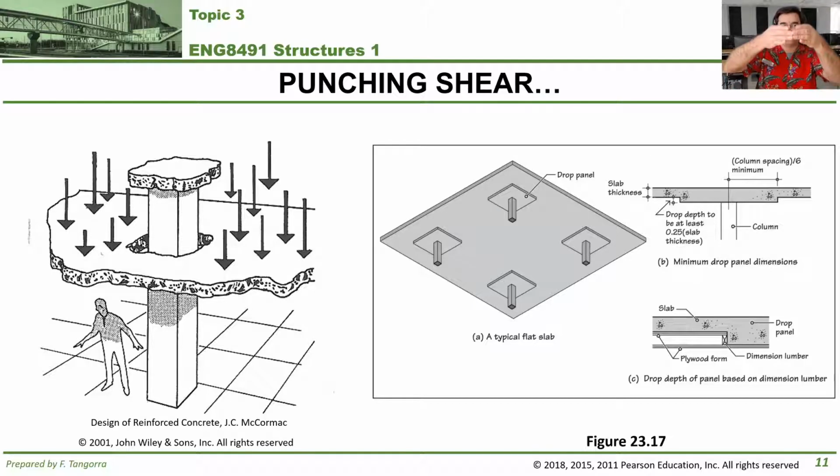But as you get closer to the slab above it, the area of the column is expanded much wider. And that's what the drop panels do. They expand that area so that more of the force from the slab is transferred on a bigger area, and you have more difficulty causing punching shear. I also provide details on the design of drop panels, so they're linked for you below.